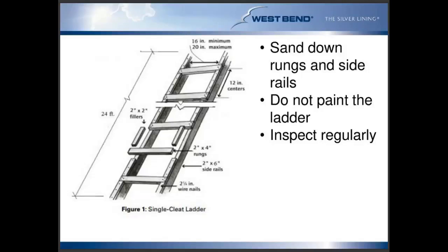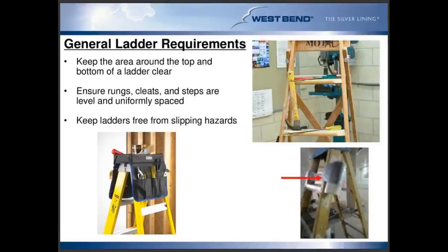You also want to make sure that you sand down the rungs and side rails. Getting a sliver while using them can also result in an injury, believe it or not. And also making sure that we don't paint the ladders. Just like all of our other ladders that we use, we want to make sure that they aren't painted or coated so that we can perform our inspections and be able to identify any damage, whether it be cracking or holes or whatever it may be, and that paint could cover those types of things up. So there are ways to use these job-made ladders safely and construct them safely. Just visit OSHA for more information or talk to your Argent Loss Control representative.